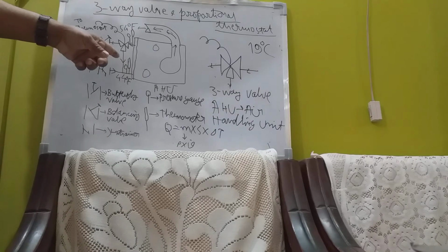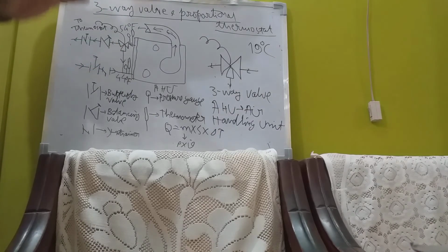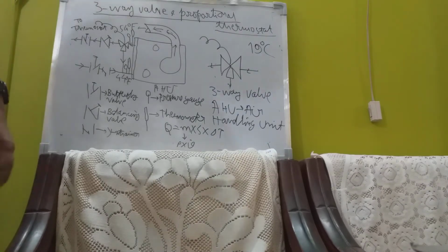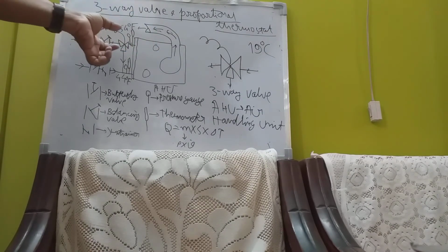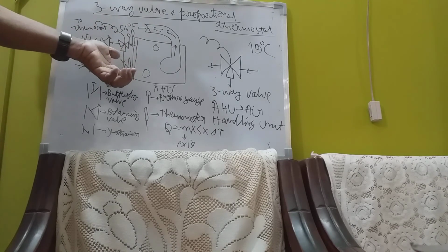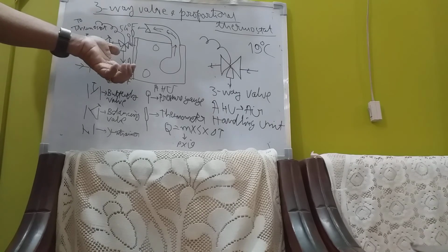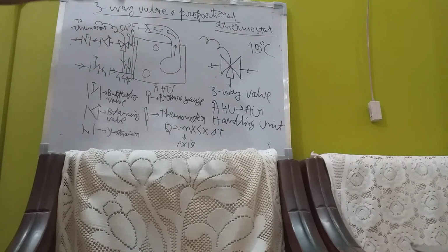Same principle as in AHU. Or opens this flow and cuts down this flow when required. But it is on or off. Isolates totally. It doesn't go gradually. In case of AHU, it closes gradually, so the water flow trickles down and then closes, depending on the requirement. But in case of FCU, it suddenly gets closed.